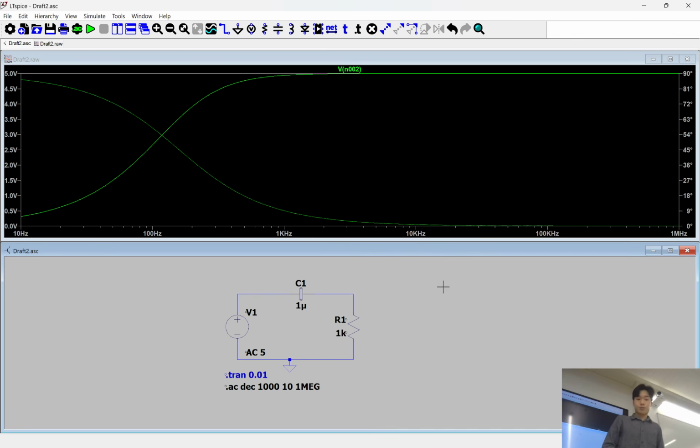All right. And on to the next exercise, just a band pass filter. Right, so what we've looked at so far is a low pass and a high pass filter. What we want to do is actually combine properties of both. So to filter out both low and high frequencies, what we can do is actually just cascade both of the filters that we have so far.